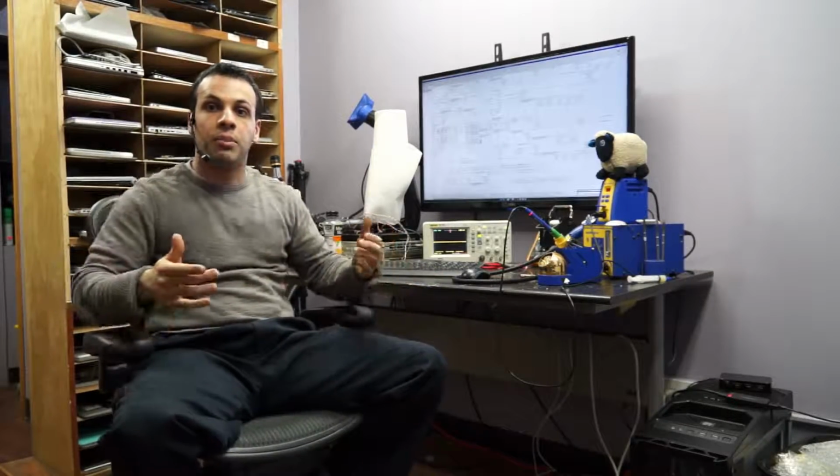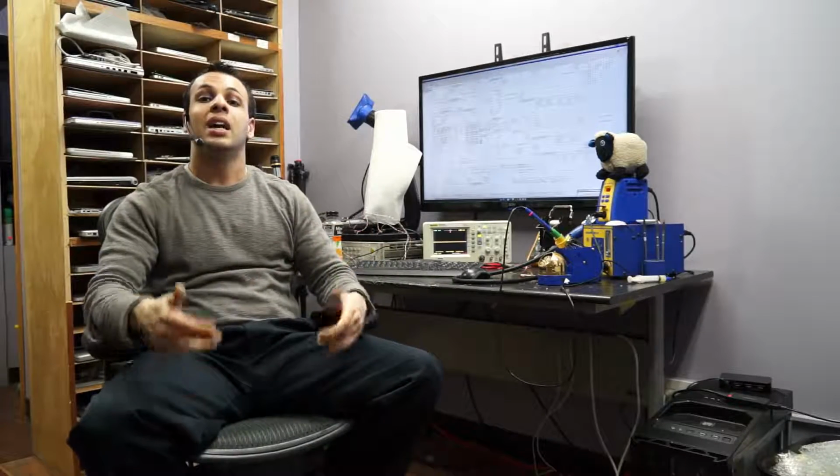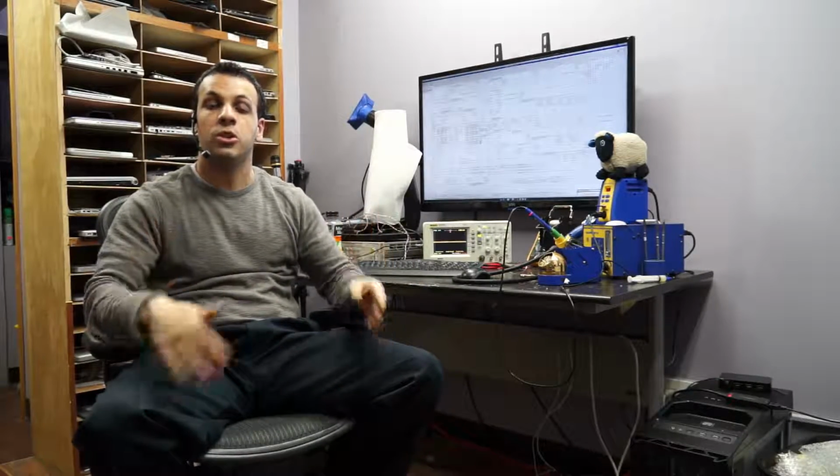Don't you want the system to turn off instead of the battery blowing up and melting your genitals? That's what R7050 and R7051 and 52 are there for, to current sense in the battery. If it's drawing too much current from the battery, it's going to turn itself off before it melts your genitals.